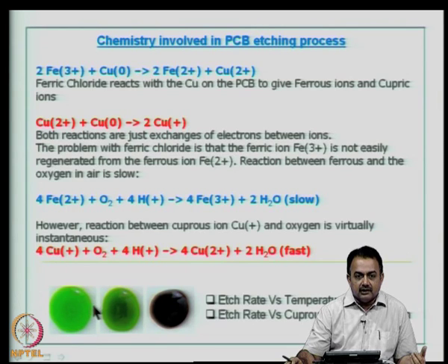As time progresses, as you start using the etchant material, you see it becomes dark, and then finally, without regeneration, you see it becomes black in color, almost brownish black, and this is the time when you have to regenerate the material.